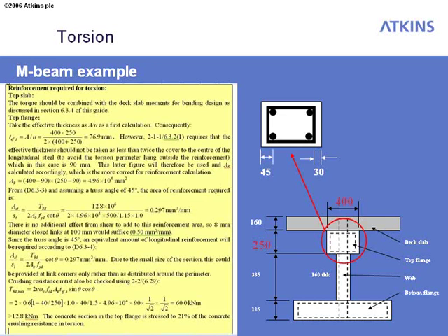We've then got to check just to make sure that we're not going to crush that rectangle with the torsion, so we need to check TRd,max. The maximum value of TRd,max that we get out is 60 kilonewton meters, which is quite a bit greater than 12.8 kilonewton meters, which is the torsion in that rectangle. So we're effectively stressing that to 21% of its maximum shear stress capacity, which means that the remainder is spare for vertical shear. 79% of VRd,max is spare for vertical shear.